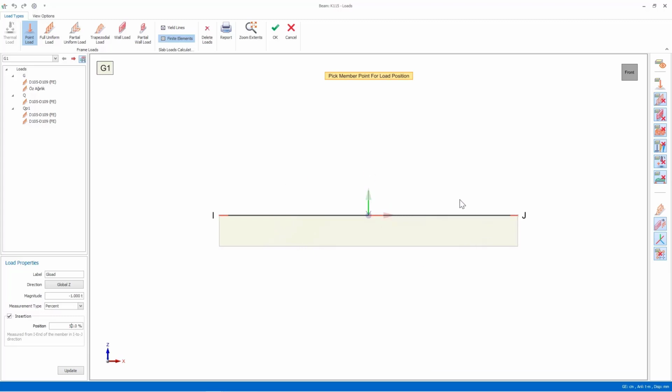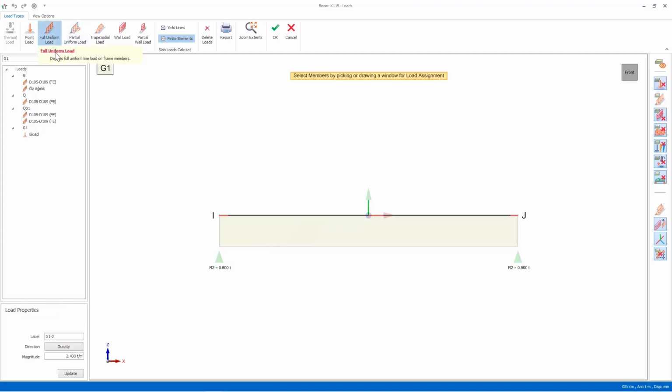At this stage, simply click on one of the smart docking points on the element to define the point load. As an alternative load definition method, instead of smart points on the beam, you can click on the beam after entering a value in the position field. The position of the point load to be applied will also be displayed on the screen.